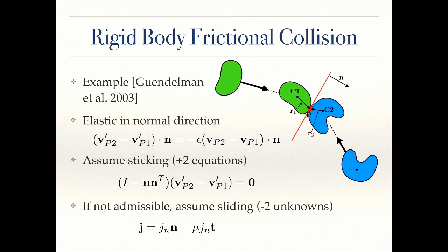If it does, we'll say, okay, we're done, we're sticking, the force is small enough, so we're not outside the friction cone, so we have enough force to stick. But if the force is going to violate the friction cone, then we'll say, oh, it must be the sliding case, and we instead have an impulse equal to this component in the normal direction, and then mu times that component for the tangential, and we solve with this, again, to find the actual frictional impulse.